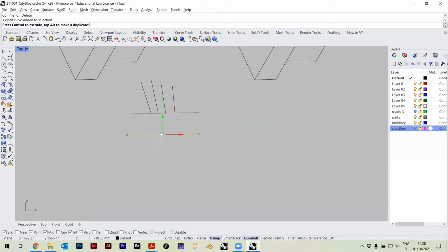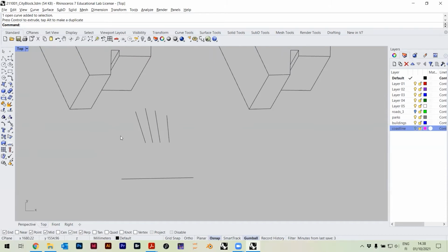So one other command that I didn't show you, you can do extend. That's the opposite of trim. So there's trim and extend somewhere. So I can say extend, and then this is the boundary. Then if I click here, I'm extending the lines here.